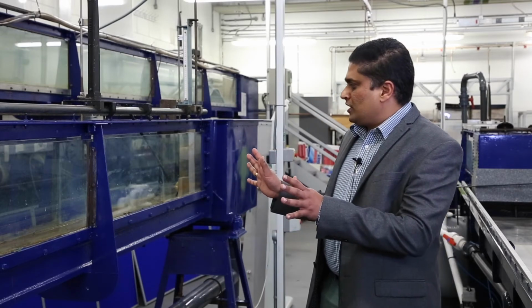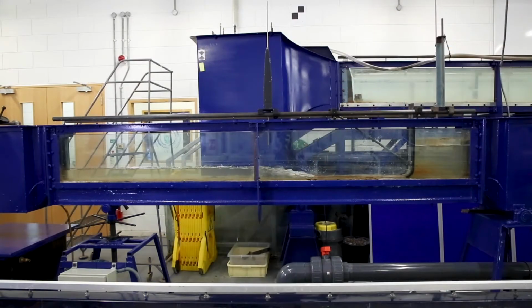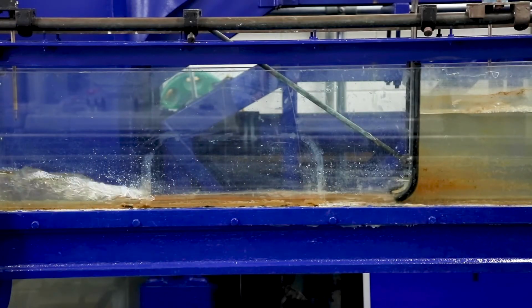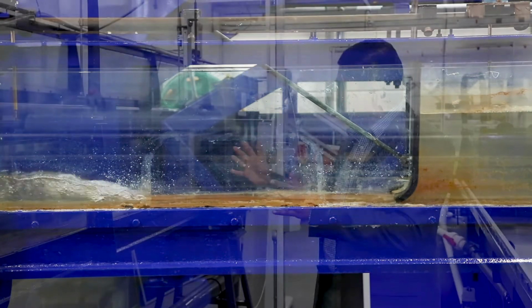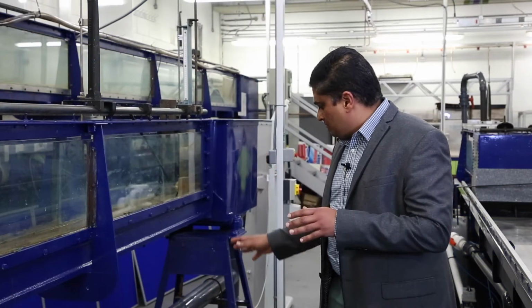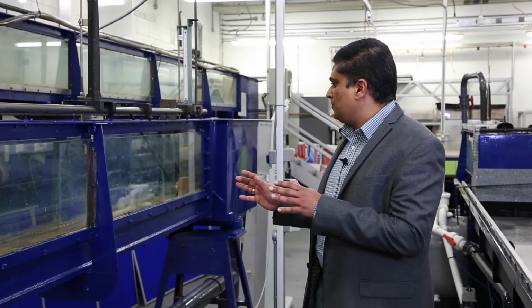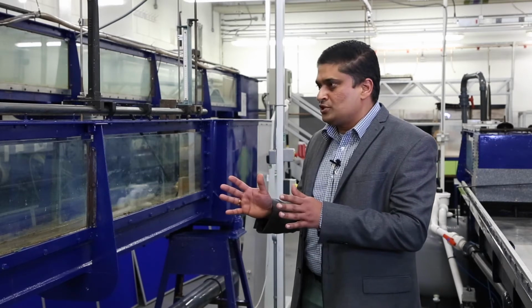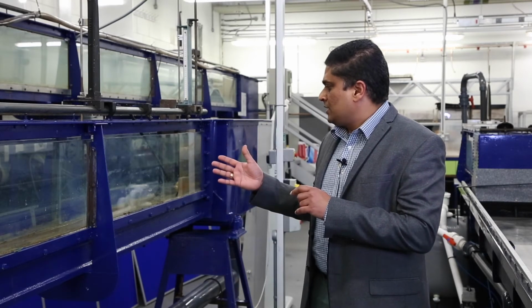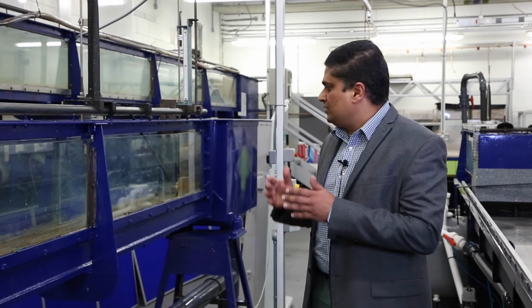So this particular open channel we use to demonstrate two different types of experiments. One is the sluice gate and hydraulic jump, where we take a number of flow depth measurements just before the gate, soon after the gate, just before the jump, and after the jump. By doing this, we will be able to calculate the velocities. Hence, we identify the different regimes of the flow. On top of that, we have the broad-crested weir experiment, where we take a number of flow depth measurements, including the critical depth. Hence, we use the weir formula to calculate the discharge.